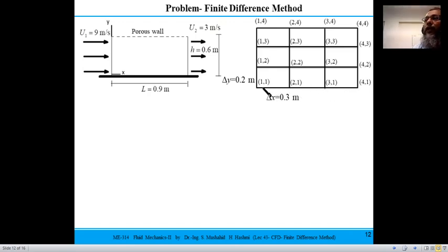But as we know, when y is 0, your stream function is 0. So at that line, whatever your numbers are, your stream function would be 0 here. So you just give some numbers, some names to each point, because I am interested in getting the value of the stream function at all these grid points.